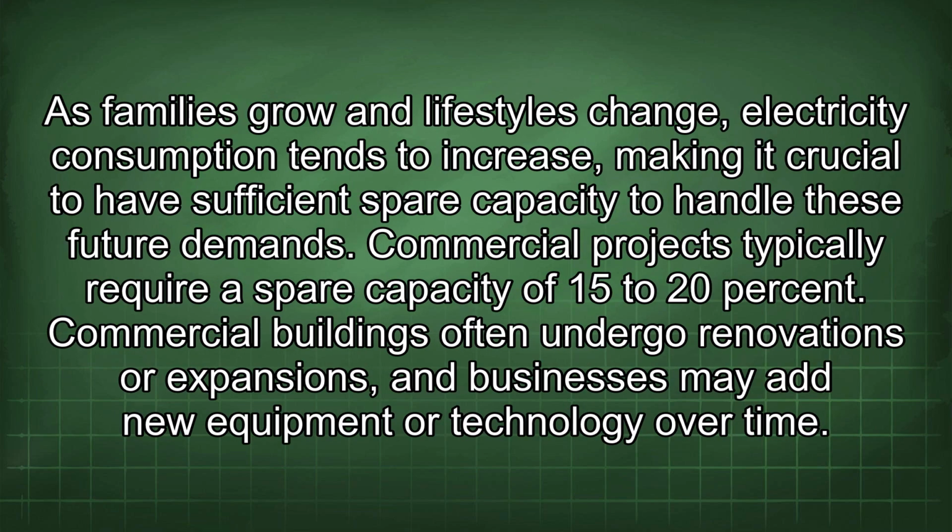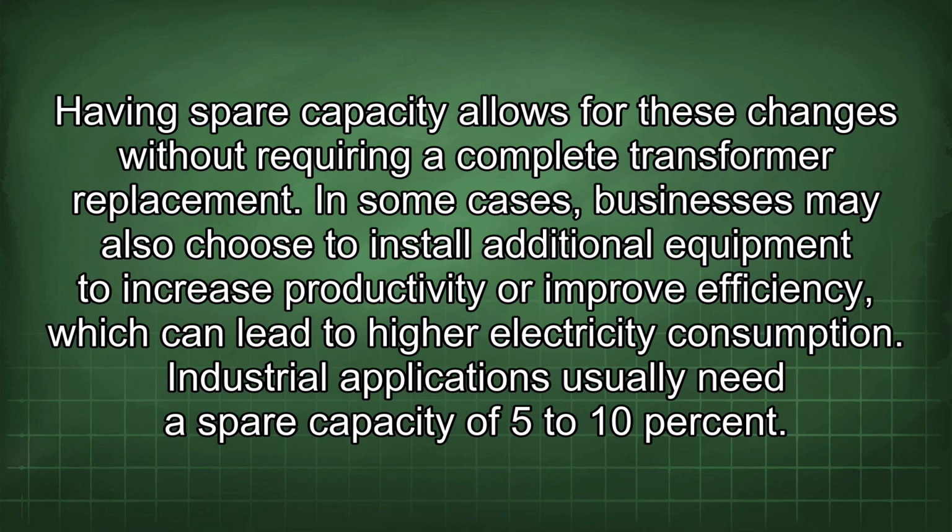As families grow and lifestyles change, electricity consumption tends to increase, making it crucial to have sufficient spare capacity to handle these future demands. Commercial projects typically require a spare capacity of 15 to 20%. Commercial buildings often undergo renovations or expansions, and businesses may add new equipment or technology over time. Having spare capacity allows for these changes without requiring a complete transformer replacement.